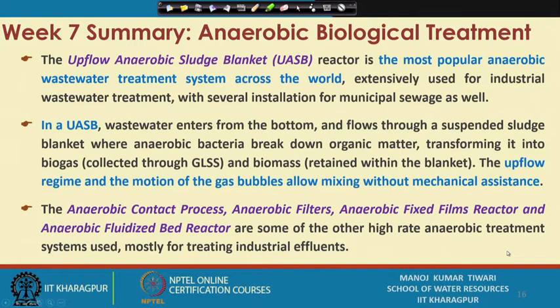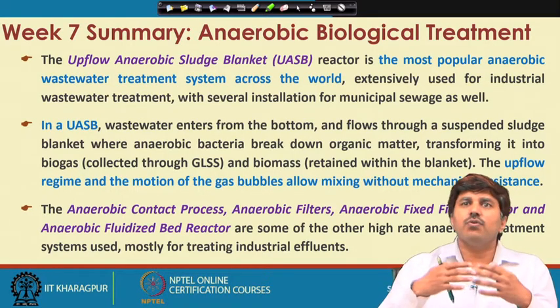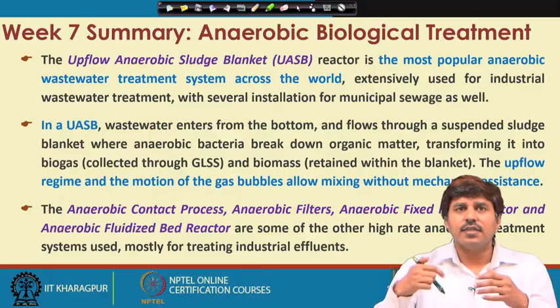Then the most common or most popular reactor configuration for anaerobic wastewater treatment is the UASB, the upflow anaerobic sludge blanket reactor. This has a single tank system where the water is pumped from the bottom and flows up through a suspended sludge blanket.